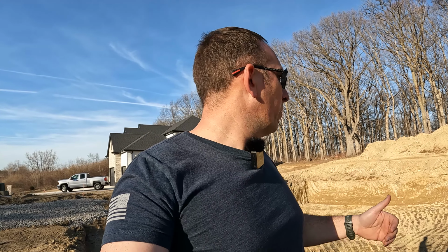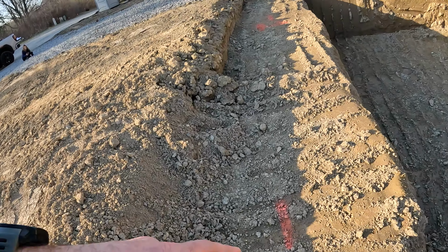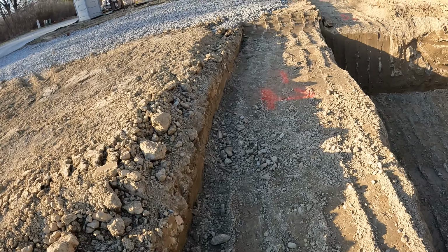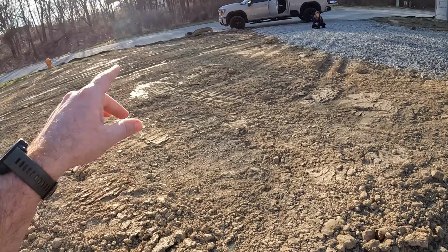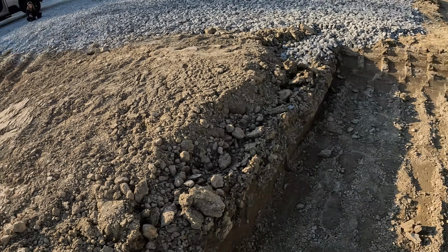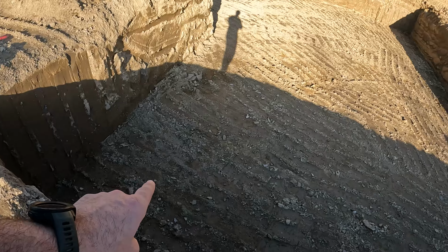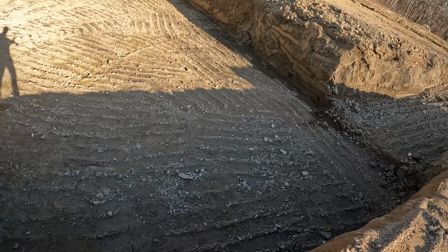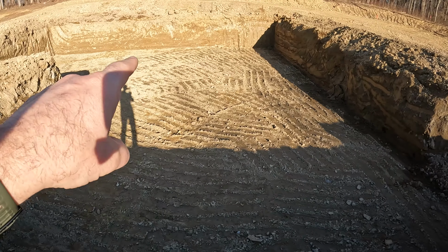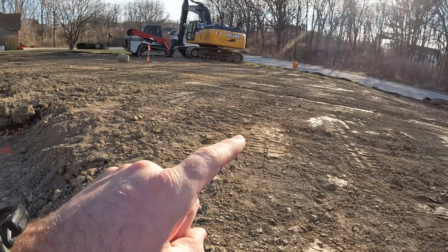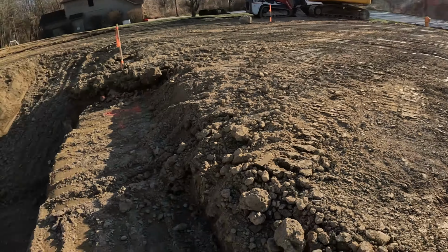Some guys still do it old school with a helper down in the hole with a stick and the laser, and he's checking it, and that's what you get. So based on the elevations shown on the site plan, that is how you end up with all of these spots. This footing location is at a set elevation in reference to the reference point out there. The footing depths for the foundation itself, same thing. They're set to a specific height compared to the elevation mark out there.